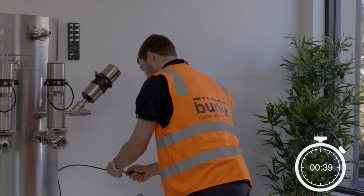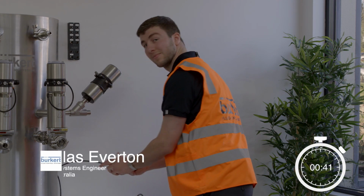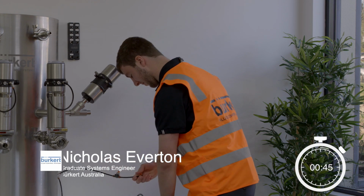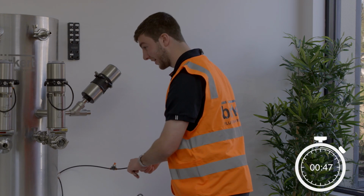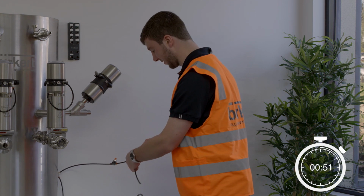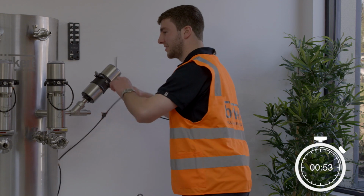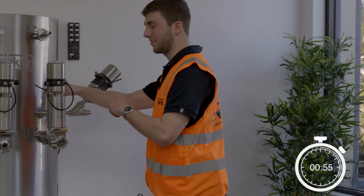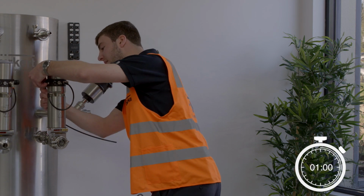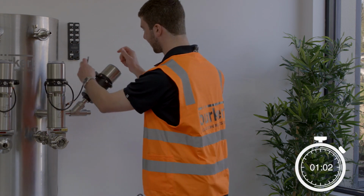Okay, so on the digital side, we have Nicholas. Nicholas, can you just give us a bit of an overview as to what you're going to do? Alrighty, so first up we're going to connect our pneumatics for our valve heads. The nice thing with these heads is that we're using pilot valves, so we don't have to run individual air lines to each valve. We can just loop between each of the control heads.